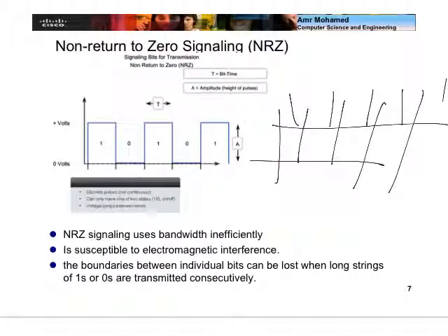So if there is any clock drift between the sender and the receiver, you can easily miss one of the bits, right? So how can we enhance this? Just to make this even clearer, how can we enhance this? We can enhance this by trying to enforce that you have to have a change of amplitude within each bit.